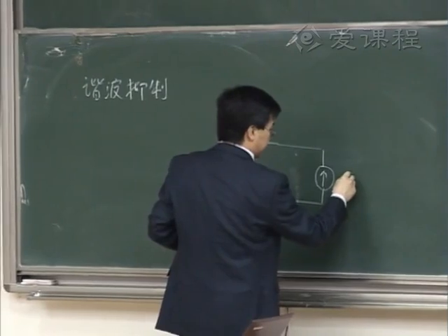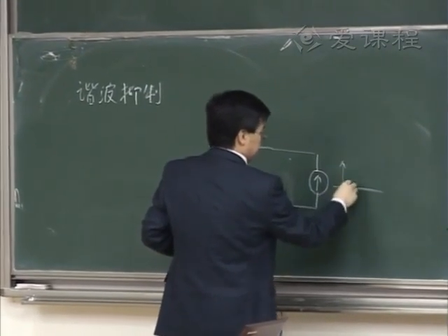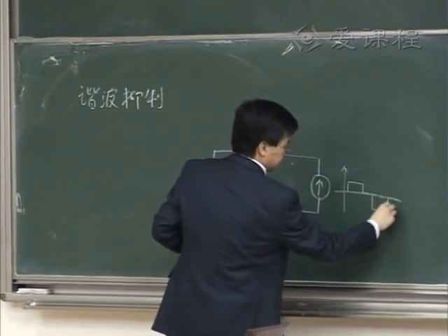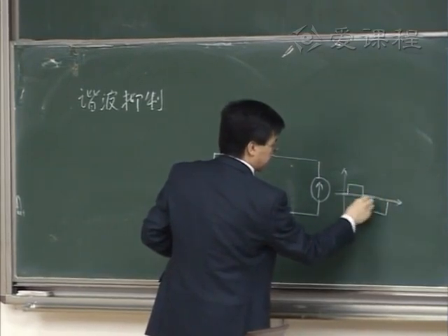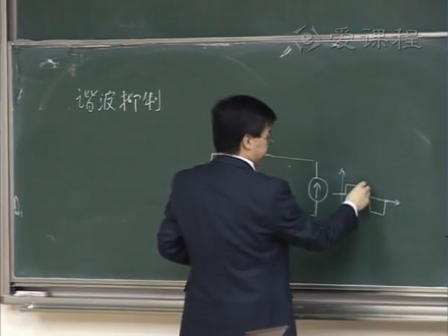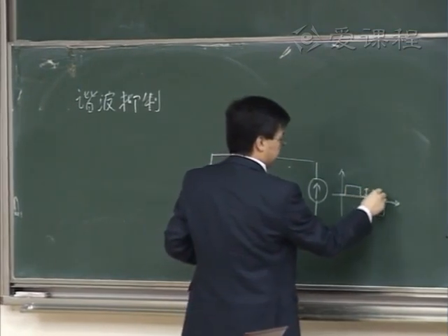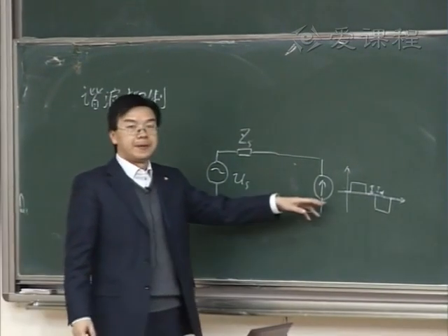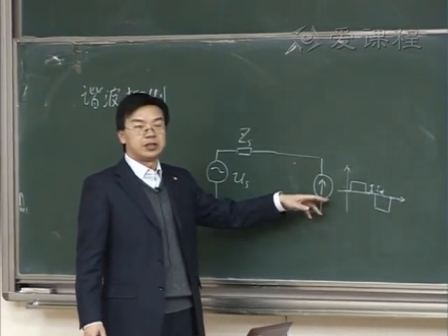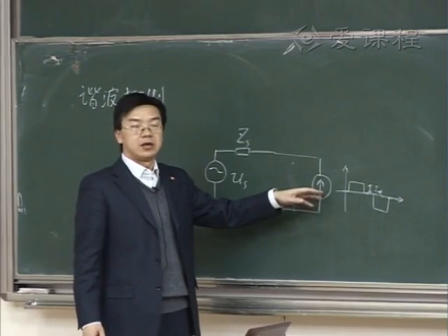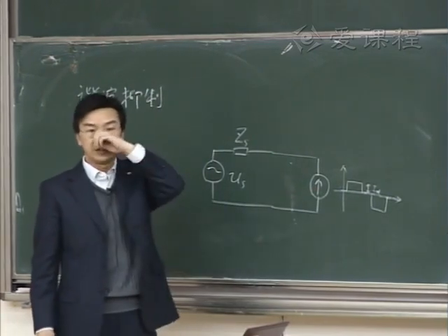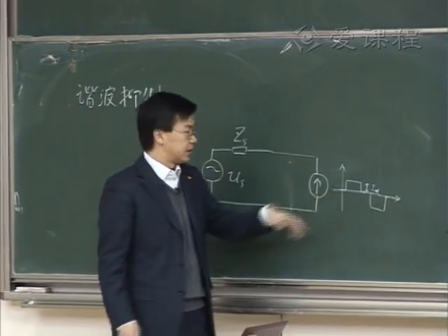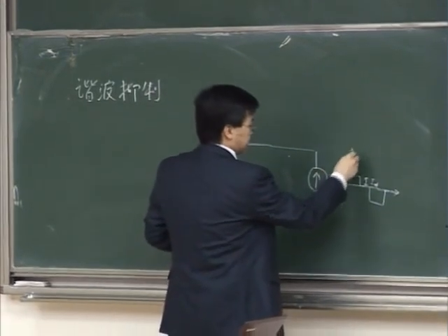If this power converter is generating current like this, this is what we call the 120 degrees current waveform. This is the typical input current waveform from a three-phase bridge rectifier, thyristor rectifier, with inductive load, when this inductor in the DC side is large enough. So usually what you have is this kind of current at the AC side.